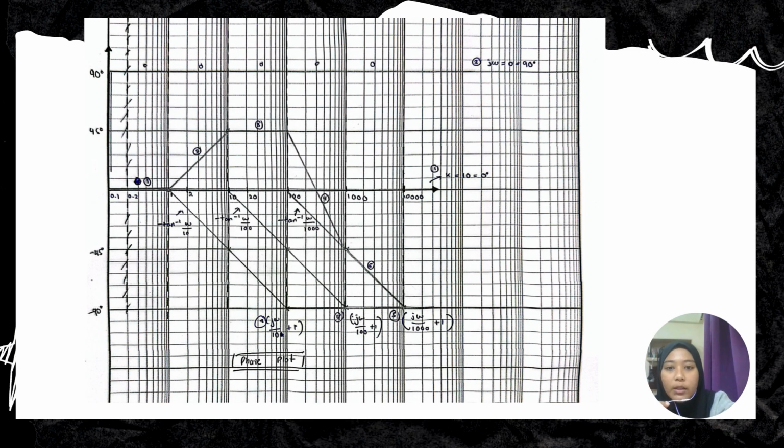Today I will explain about the plot. The figure represents a Bode plot where the system response is analyzed in the frequency domain. The horizontal axis is the logarithmic frequency scale, while the vertical axis represents the phase angle in degrees. At low frequency, the phase is close to 0 degrees, which means the output signal is nearly in phase with the input. This indicates that the system behaves normally without much delay at low frequency.